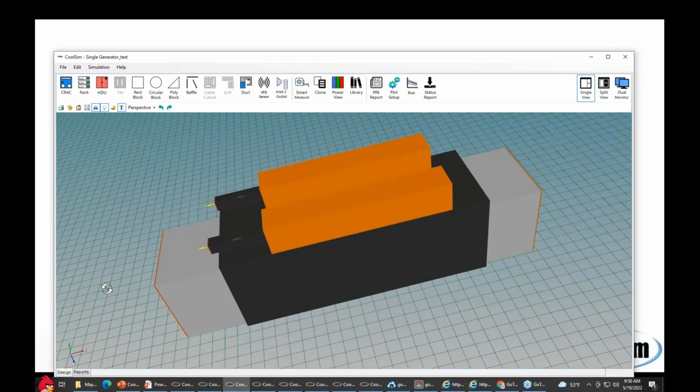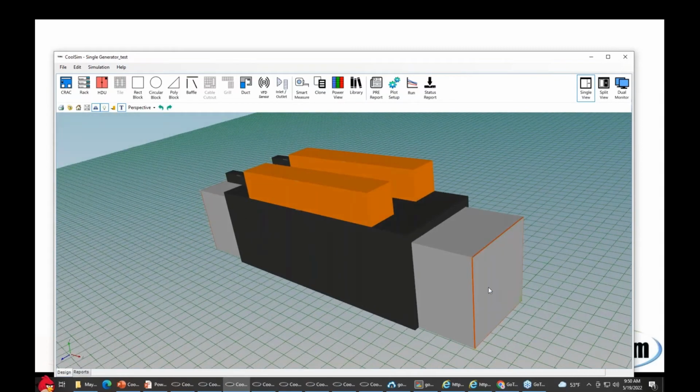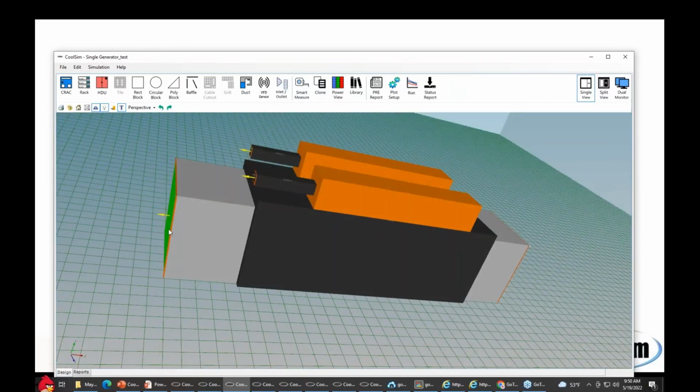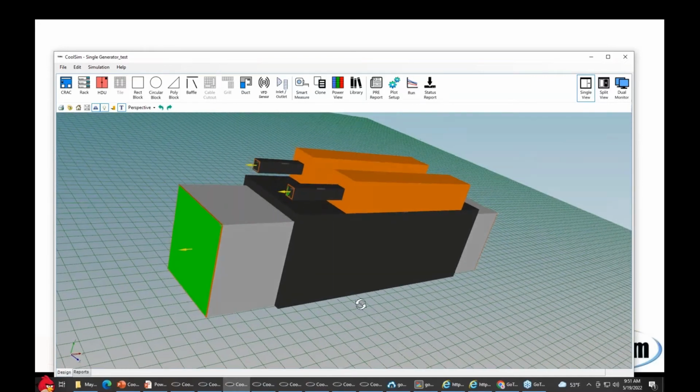So this particular structure of a generator has air coming in through the back here, through a heat exchanger, passes over the motor, which sits in a box. This is a diesel motor, diesel generator. And then it has a heat exchanger on the front that dumps the temperature of the water jacket. So the generator, if you remember, has a water jacket, dumps that heat. And then the most important is the exhaust that comes shooting out of the pipes.